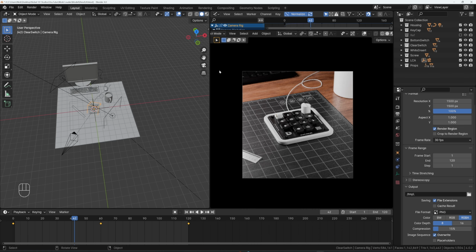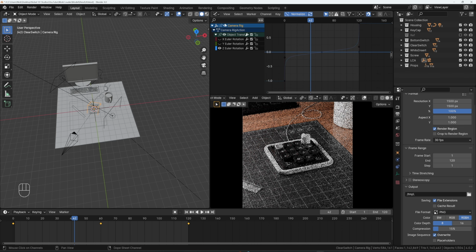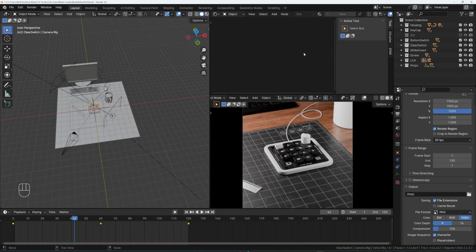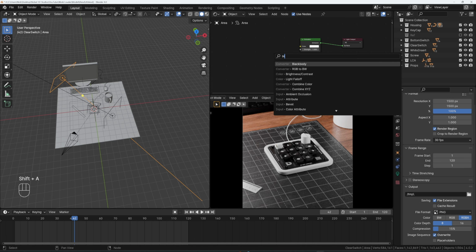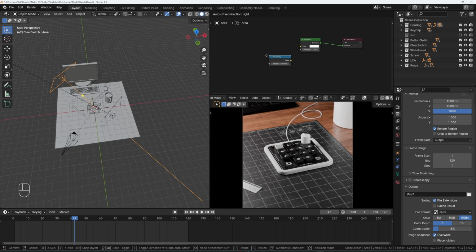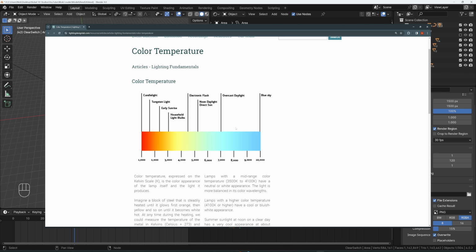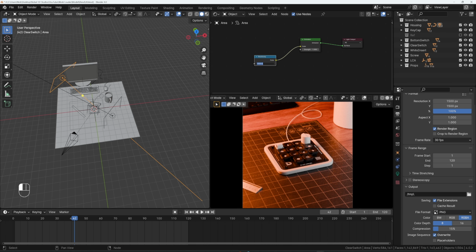So now the only other tip that I would add is we're going to do this real quick. This is a new thing I've been messing around with. So if we grab this light and then click use nodes, what we can basically do is instead of these just being plain white lights, what we're going to do is Shift A and then add in, search for black body converter. And then now if we plug this color into this color, like, this is going to go absolutely bonkers. So I'll put it on the screen now, but basically we can use the Kelvin temperatures of light to color the light to kind of be realistic. So let's just play around with that.